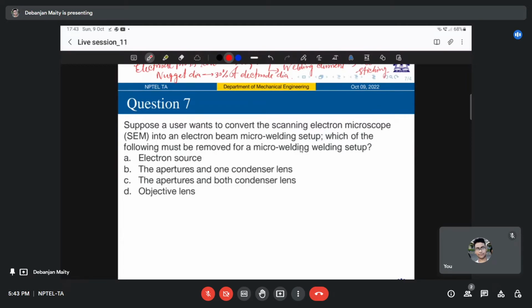Here, the welding is realized by a laser generated liquid metal droplet, which is deposited onto the parts to be joined, right? So there will be a liquid metal droplet creation because of that laser, and it will deposit over the parts. And the raw material is a metal wire.